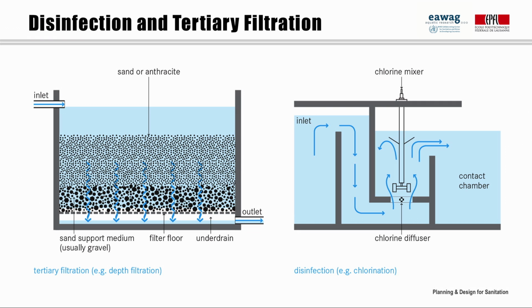On the other end of the treatment process, there are different possibilities to polish the effluent, the so-called post-treatment technologies. Depending on the desired end use of the effluent or on national standards for discharge in water bodies, a post-treatment step may be required to remove pathogens, residual suspended solids, or dissolved constituents. This can be mainly achieved through tertiary filtration and disinfection techniques.